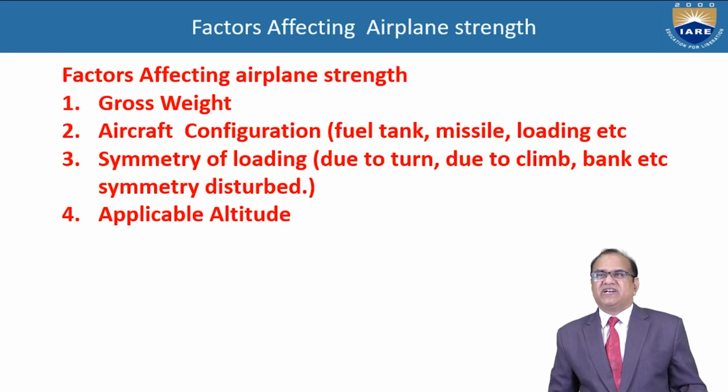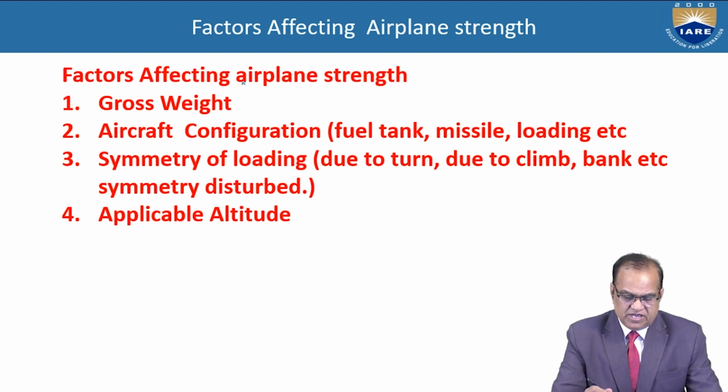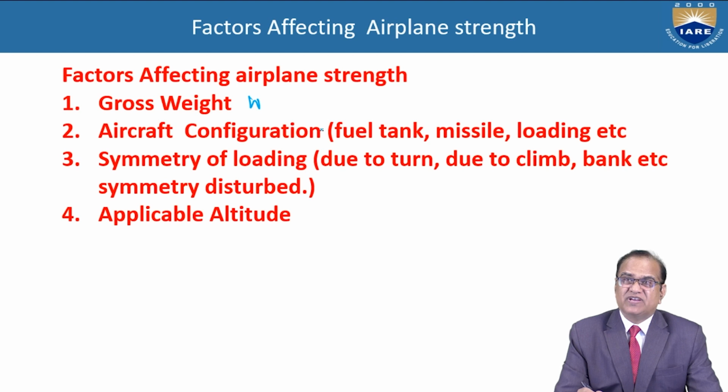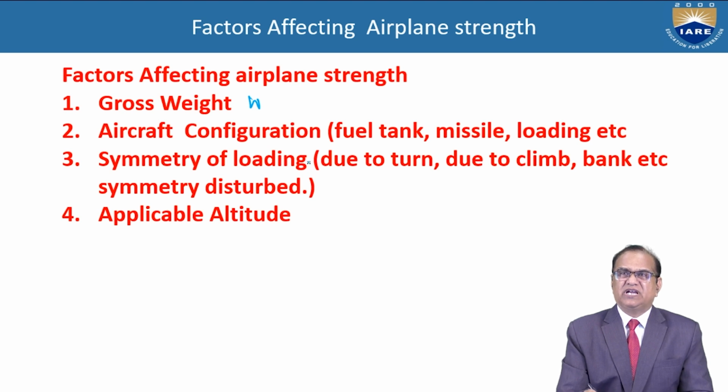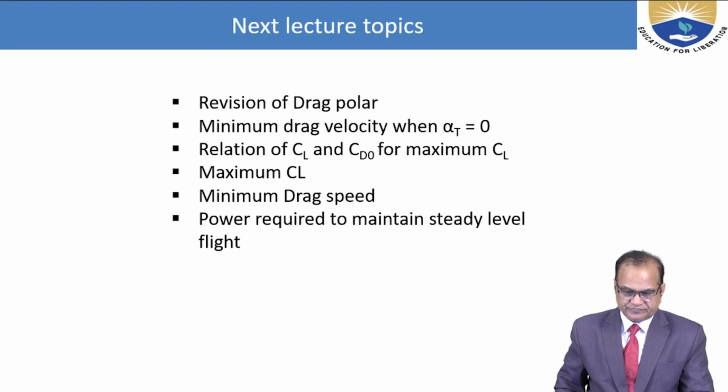Factors affecting airplane strength: gross weight, the W of the aircraft; aircraft configuration, the fuel tank, missiles, loading and so on; symmetry of the loading, due to turn, due to climb, bank, and so on, your symmetry will be disturbed; and applicable altitude, so rho also matters.